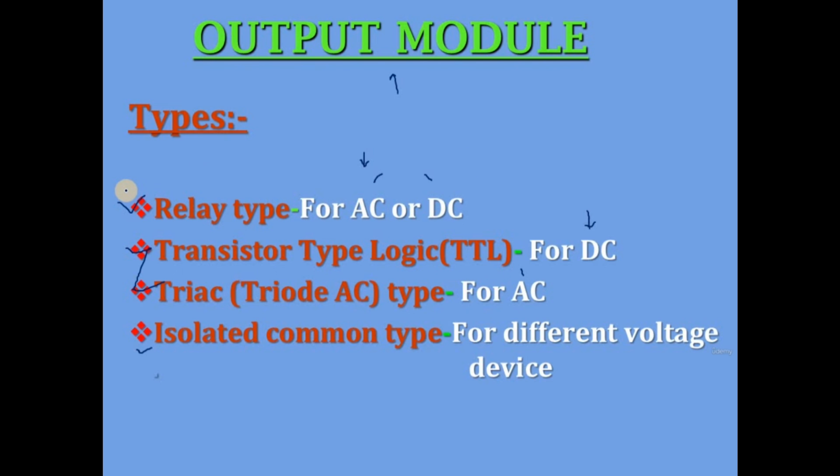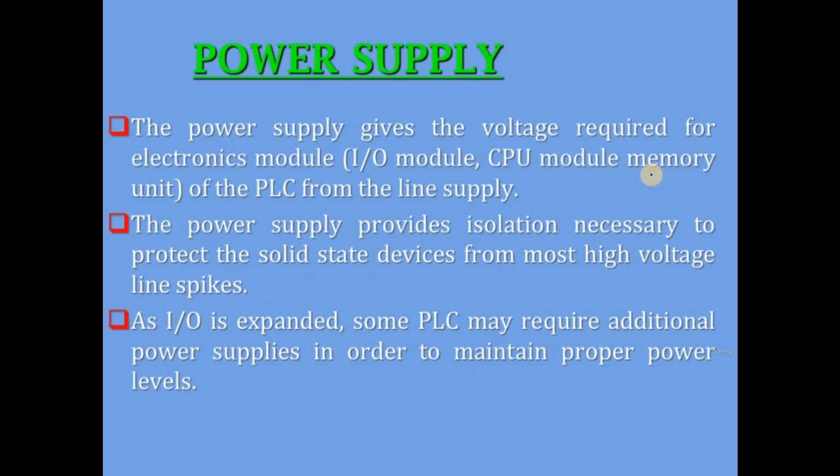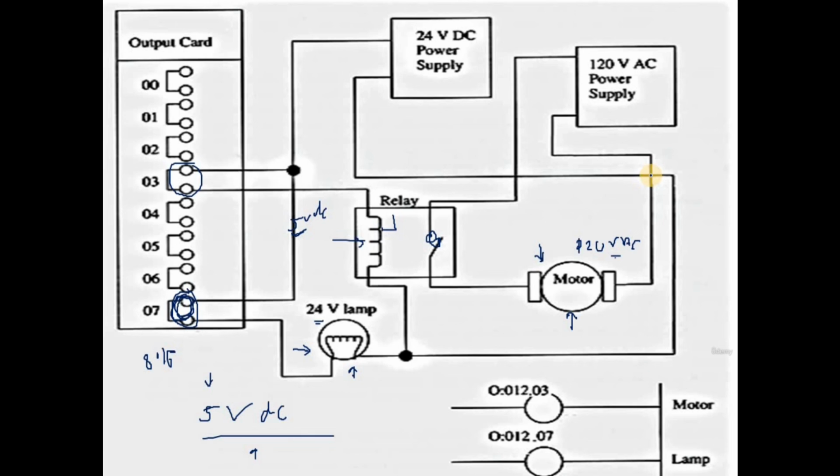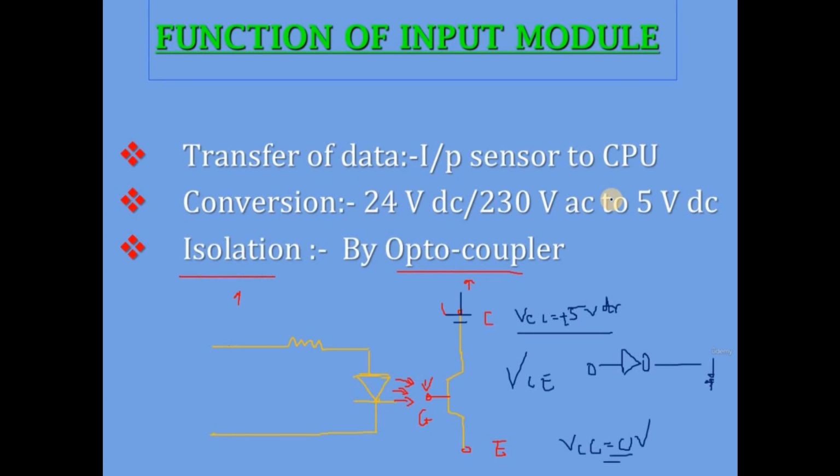Okay. If you are observing the relay type cards in the software, we have to recognize them by this RLY. And for the transistor type, you will get it like this: trans. You can observe the trans in your output card. The trans means the transistor type output card, and RLY means the relay type output card. Now before moving to the next component, we need to understand the concept of sink and source, right?